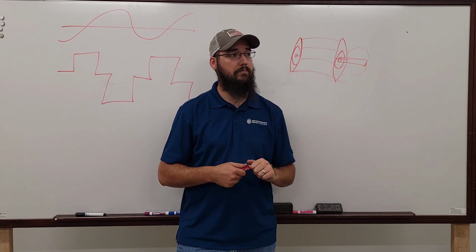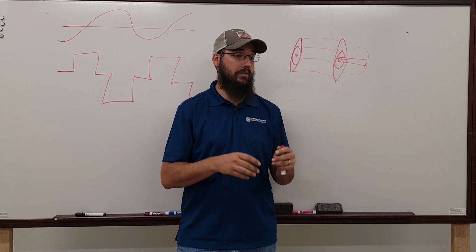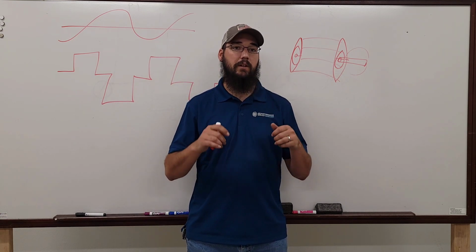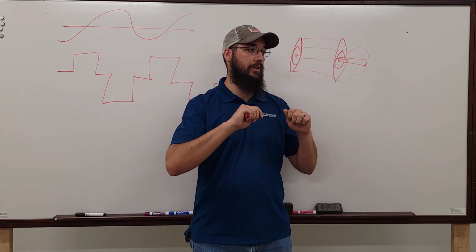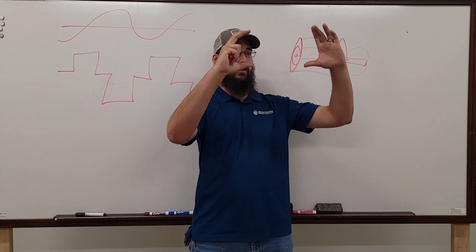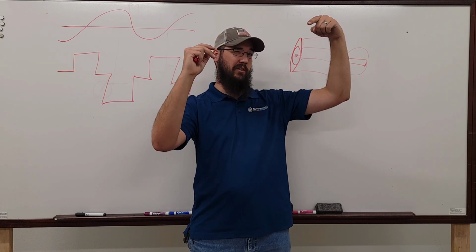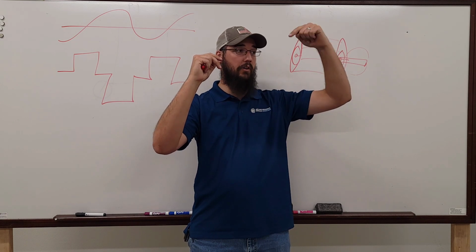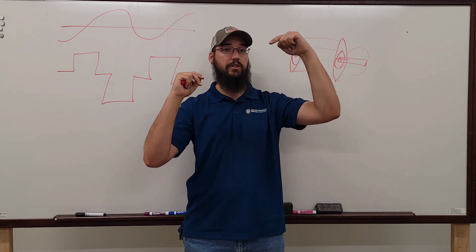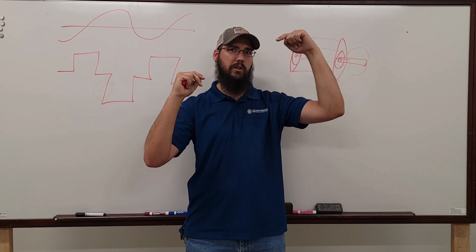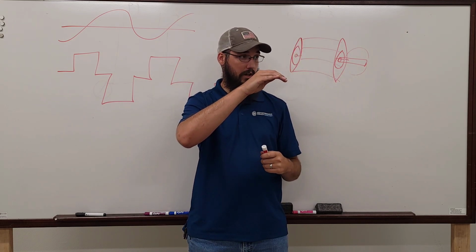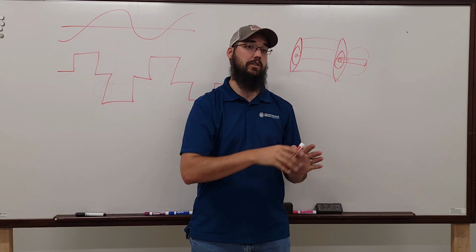How does that floating point look? Like, is it just like a little metal thing tapped in the side of the shaft, or how does it actually physically look? Yeah, so you'll see a steel ring that'll be screwed. They've tapped some holes and it's screwed over the shaft, centered. And most of the time, I think they're usually like a brass type material. They're usually a softer material than steel, so they don't wear into the shaft. I think they're usually a brass or bronze, something of that nature. And that's all it is. It'll have a slight curve to it naturally from the factory. That way it marries to the shaft better.